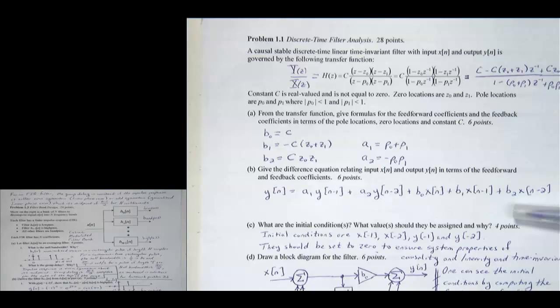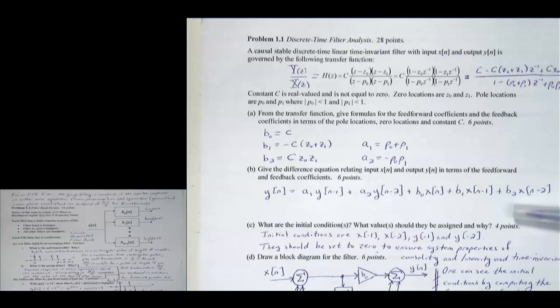And again, any low-pass filter will do as the prototype filter. And implementation is also not so bad. These are all FIR filters. Now, as the number of channels grows too high, the FIR filters become long, but you can do 512 channels here, and we can do 512 tap FIR filters, no problem.